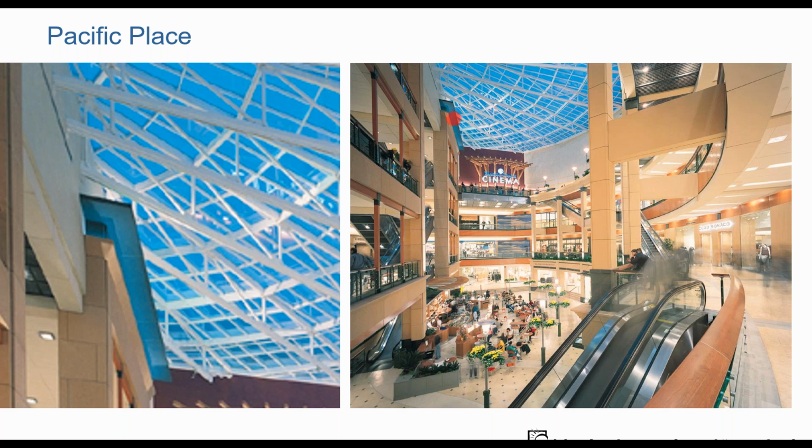We basically designed it so that the actual output of the neon that we wanted was going to be about half of the full output, which was very difficult, again, to get that programming bit to stick. And the daylight threshold controls for lighting across the truss, they basically kept essentially mucking that up in such a way that the lights would be burning all the time.